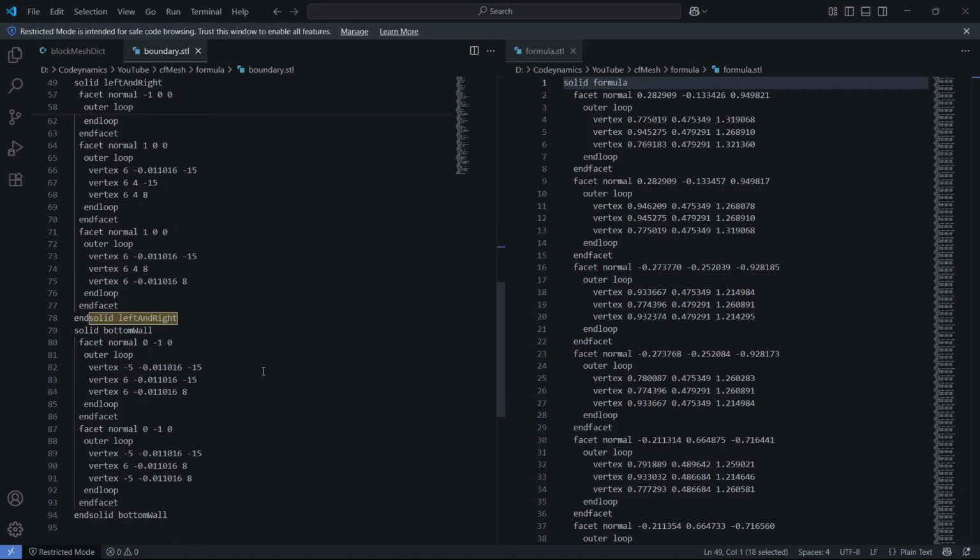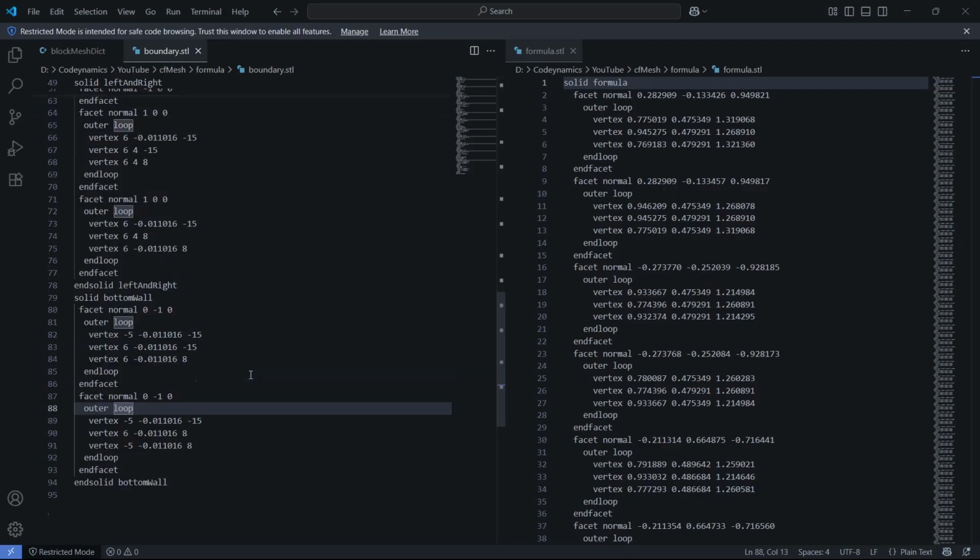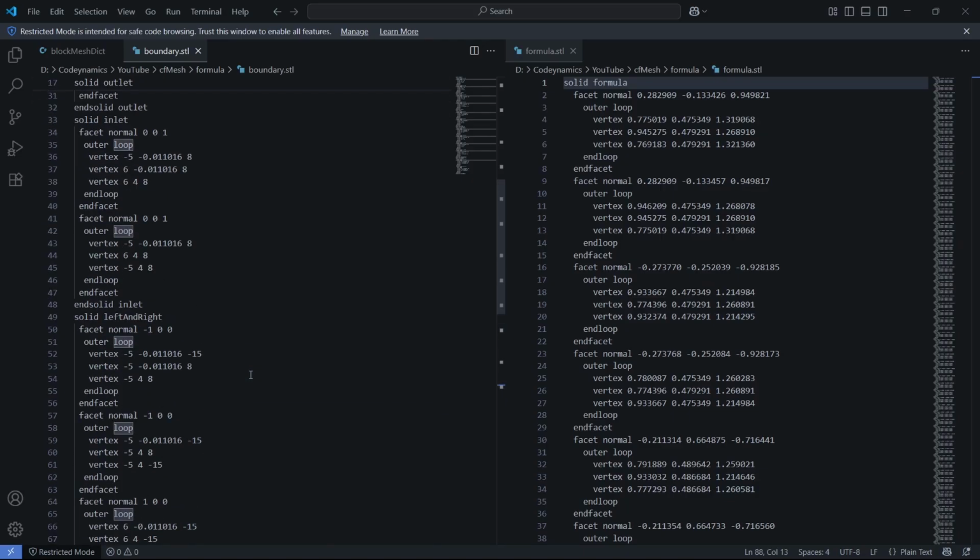So this is how an STL is stored. It takes the vertices and then it creates faces. A set of three vertices will make one face, which is a triangle, and then it will store the face normal to say which way the face is oriented, and then it will form the whole STL. That's how it is made.